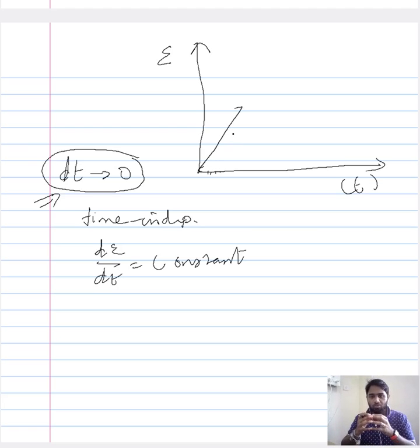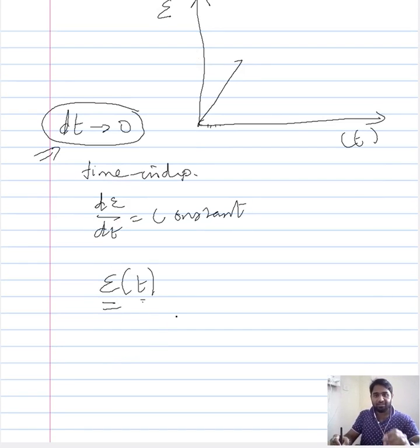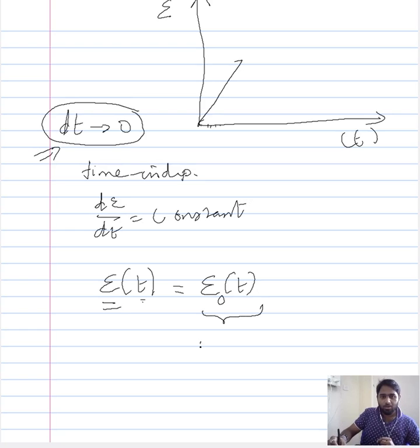Now this part of the curve we identify to be instantaneous creep. So what Andrade wanted to do was arrive at an expression for the overall change in the strain during the creep testing. He wanted to arrive at an expression for the overall creep curve based on the change in strain with respect to time. And the first stage he identified was a stage we can refer to as epsilon naught. The strain at this stage, epsilon naught, was independent of time.